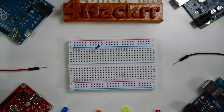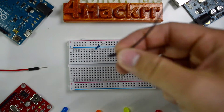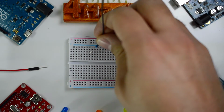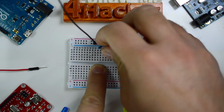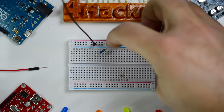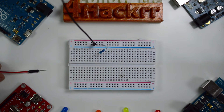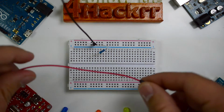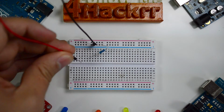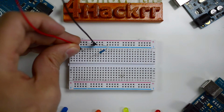Okay, the next step is to connect the wires to the Arduino board. I'm going to use the ground, which is the black one, and I'm going to put that one on the ground lane here, and that is to match this line here where the ground is connected on the resistor. The next one we're going to do is the positive, which is the red one, and this we're going to connect to the positive lead on the LED, and we're going to put it right next to this line.